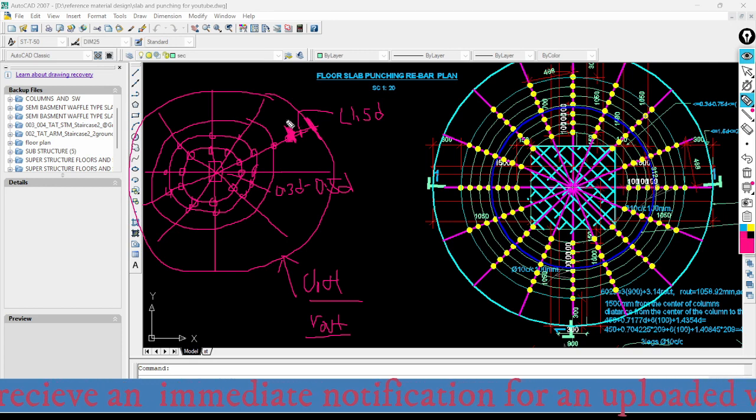So the distance between this point and the face of the column, which is r, is equal to what? R out minus 1.5 times d. That is this distance. So R out can be obtained from CSI SAFE.